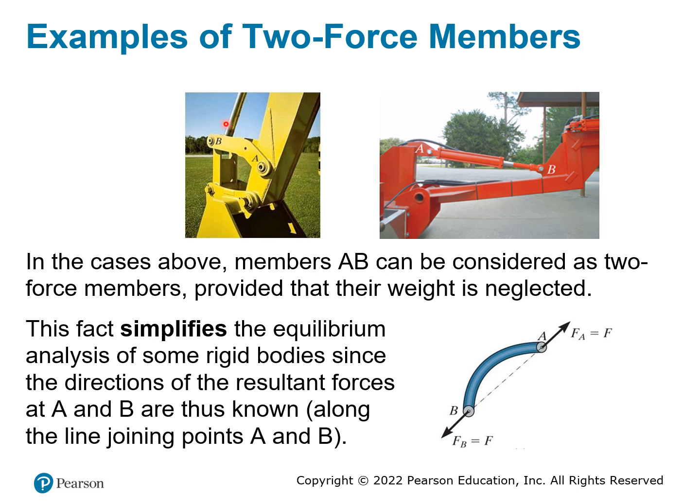And that means you're going to have 4 different reaction forces. It's very complicated because you have 4 different unknowns. If you want to solve it, you need 4 equations. However, if this is 2-dimensional, you only have a maximum of 3 equations to solve the problem.